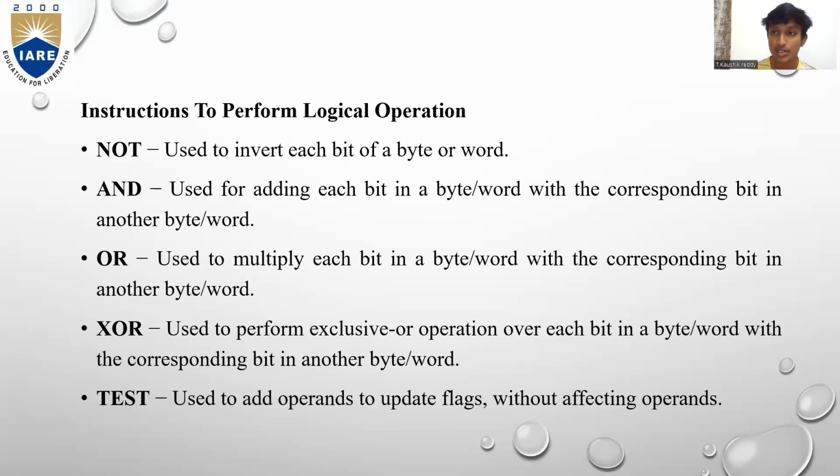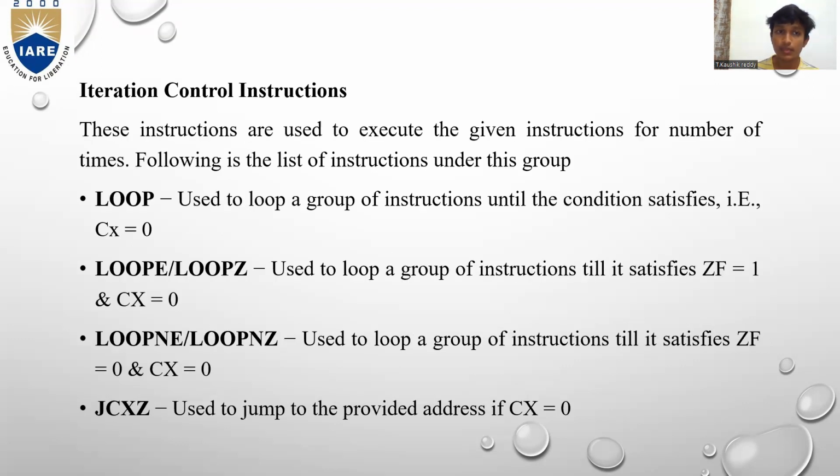Instructions to perform logical operations. NOT is used to invert each bit of a byte or word. AND is used for multiplying each bit in a byte or word with the corresponding bit in another byte or word. OR is used to add each bit in a byte or word with the corresponding bit in another byte or word. XOR is used to perform the exclusive OR operation over each bit in a byte or word with the corresponding bit in another byte or word. TEST is used to AND operands to update flags without affecting operands.